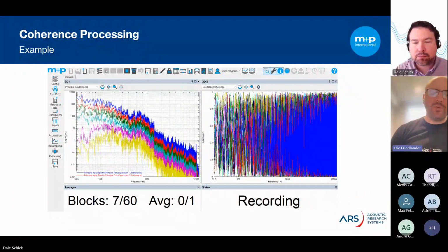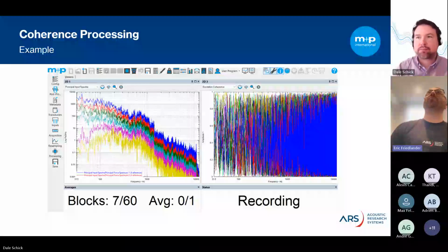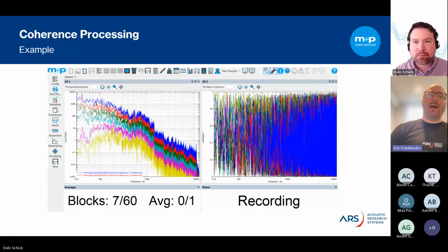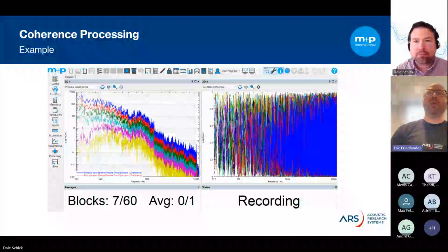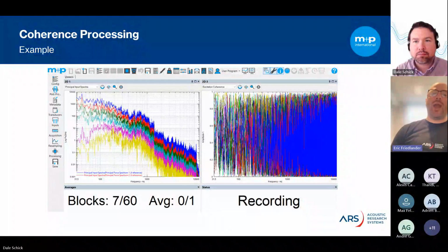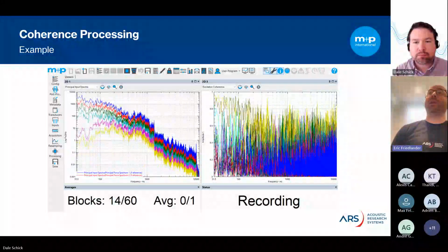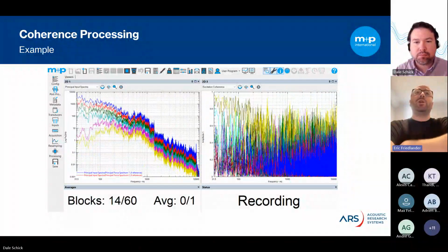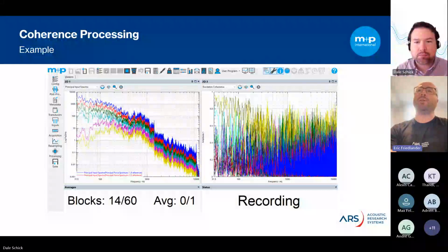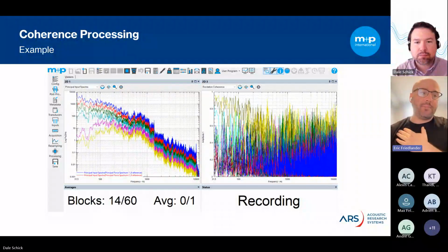It's also important, just a reminder from my notes here: if you over average and over space mics apart, it's possible to make things look less coherent than they are. And if you under average, or if you put a whole bunch of mics right on top of each other, they might show a high coherence because they're seeing similar parts of the field. So there's more than one way of looking at it, but it's important to keep some of those practical considerations in mind. Next slide, please.